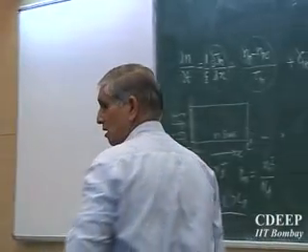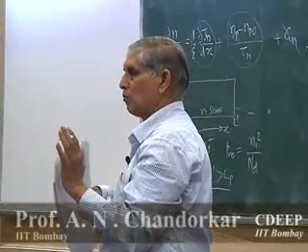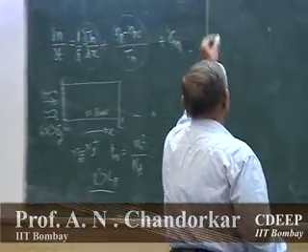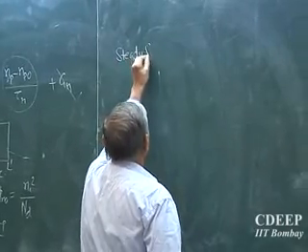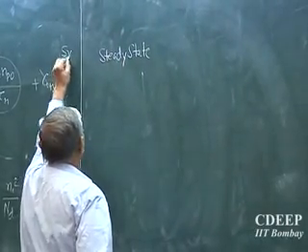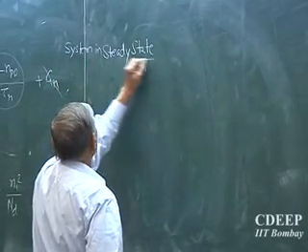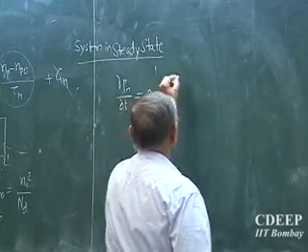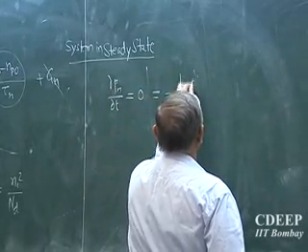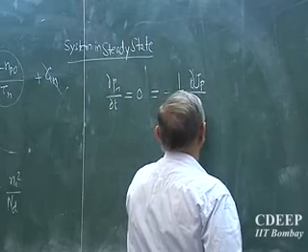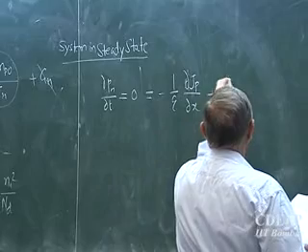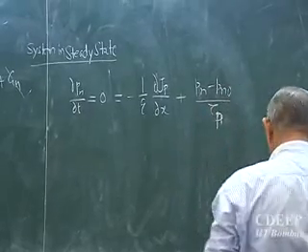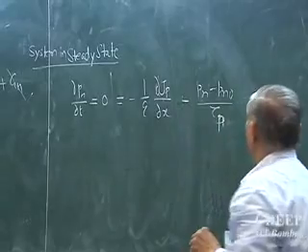So which state are we now in? Constant light, constant carrier generation, recombination going on, and carriers are diffusing out. So it is in steady state. So the system is in steady state. And because of that we say dPn/dt = 0 is minus 1/q (actually it should be partial, but if you keep writing otherwise, don't worry too much) plus (Pn minus Pno)/tau p. Oh, this also is opposite charge, so minus.